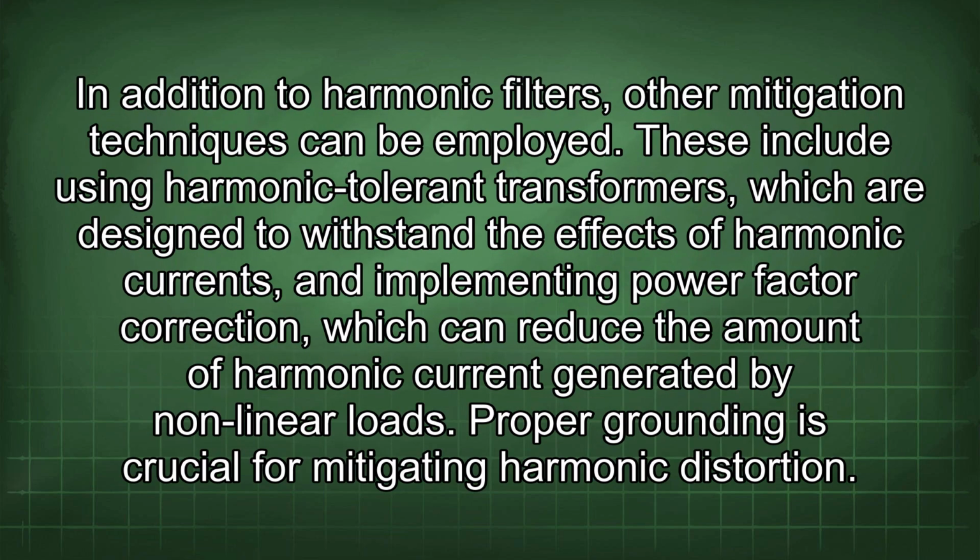In addition to harmonic filters, other mitigation techniques can be employed. These include using harmonic-tolerant transformers, which are designed to withstand the effects of harmonic currents, and implementing power factor correction, which can reduce the amount of harmonic current generated by nonlinear loads.